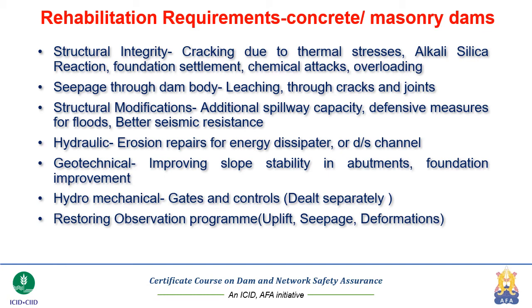Another major issue of rehabilitation is the seepage through the dam body. Primarily, any gravity dam sits on and remains stable by way of its weight. The strength part of the concrete is not brought into play very greatly, but the weight is very important. And when seepage occurs through the dam body, it creates leaching, and this leaching and cracking coupled will create an unsound dam, and for that the seepage has to be arrested. For arresting the seepage, there are various aspects like providing a membrane, carrying out grouting, carrying out the surface sealing of the cracks, and so on.